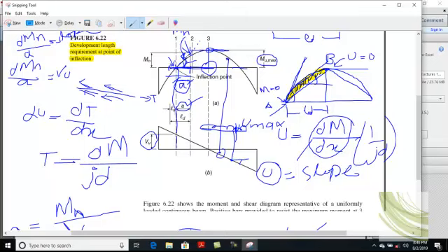This distance La you see here is a kind of extension behind the point of inflection. So this extension makes you more safe. If you do not extend, your a must be equal to or greater than Ld, then you are on the safe side. Your bond failure would not occur. Clear?